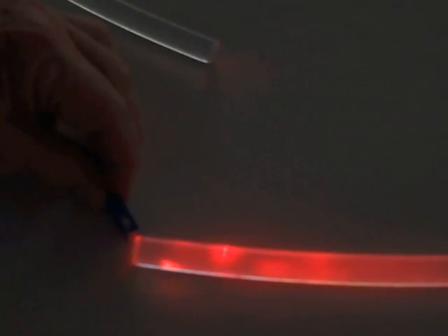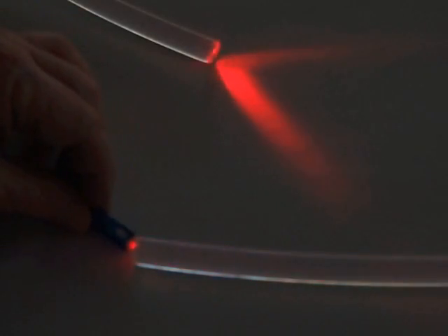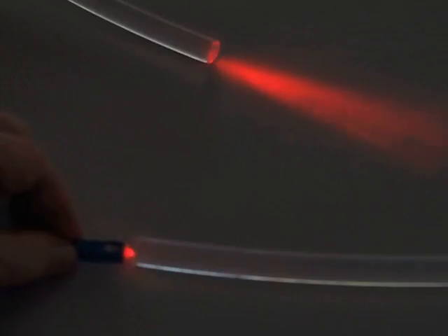The difference in the index of refraction of the two materials in the core and the cladding cause the light to be trapped inside the core. So now I'm just going to reduce my angle a little bit. It didn't take much, and now we have total internal reflection again. And that's how it works. A simple demonstration with a visual fault locator and a large core plastic fiber.